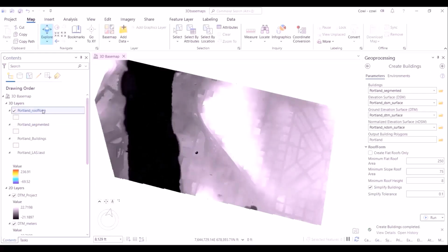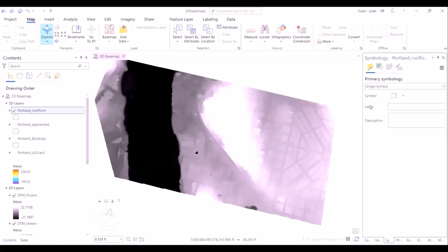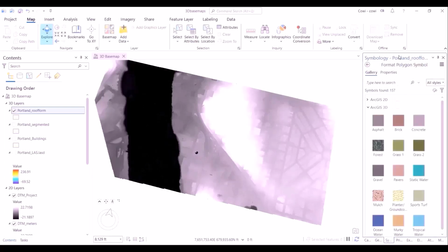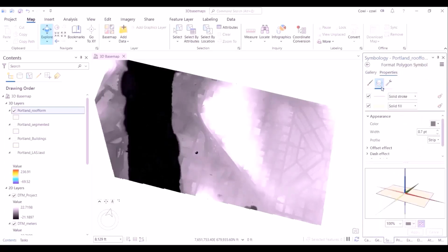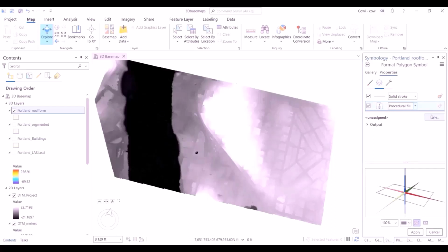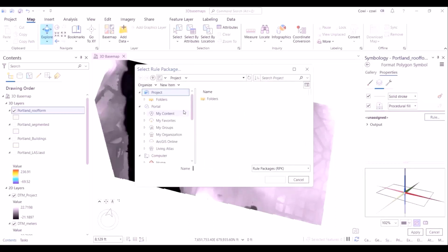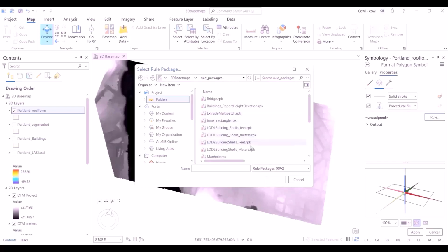Once the tool runs, we will be able to use the symbology to depict it on the map view, because currently the map view is 2D in nature, but the new layer which we've created is 3-dimensional in nature. So we need to configure the symbology so as to allow the software to depict the newly generated 3D building footprint layer in a nice 3-dimensional form.